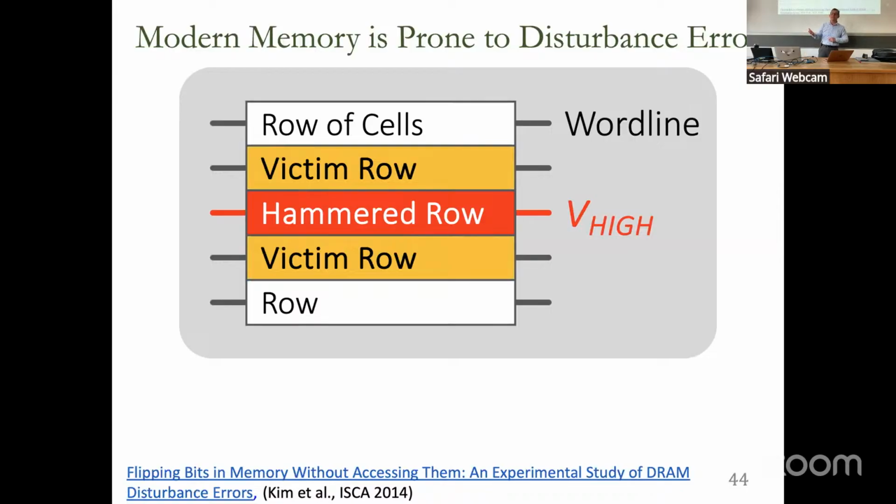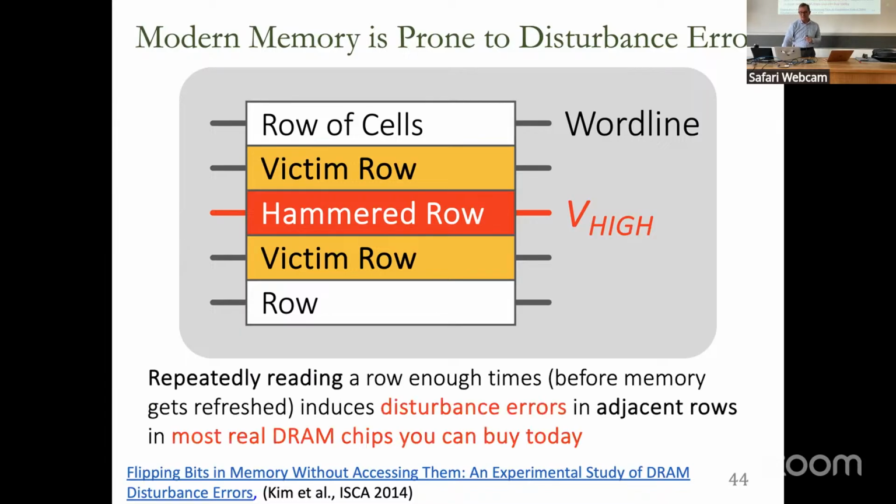And the reason this is happening is cells are essentially too small and too close to each other. That's basically the essential reason. There are many device level reasons that we'll not get into. Crosstalk, for example, electromigration. These are the two major reasons. And these keep changing also as technology evolves, meaning there are other reasons as well, and some of them become less dominant or more dominant at the low level. If we have a RowHammer lecture, maybe we'll go into that. But basically, cells are too small and too close to each other. The fact that you're accessing one cell is affecting the other cells because they're too close to each other and there's noise happening. Okay.